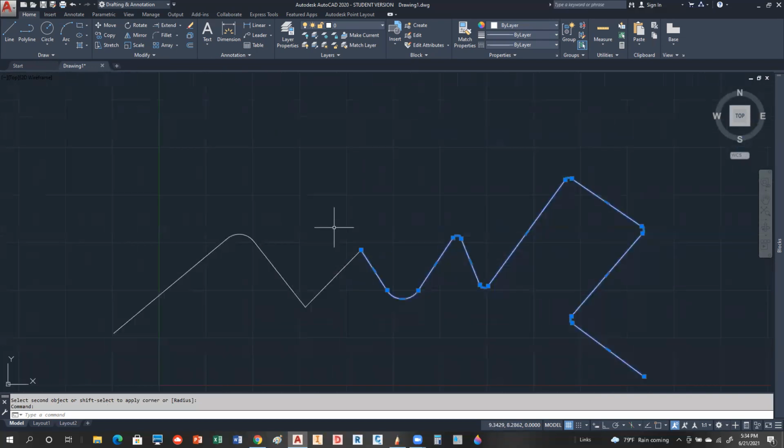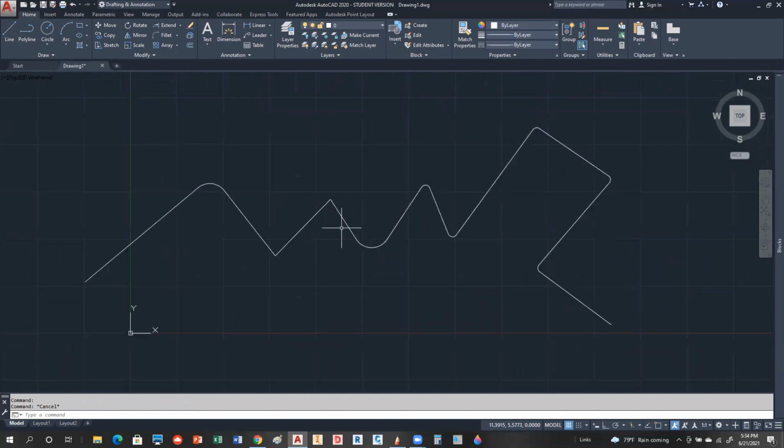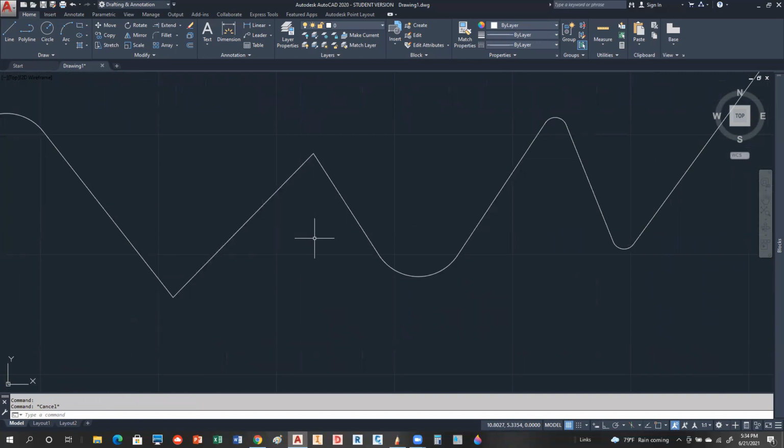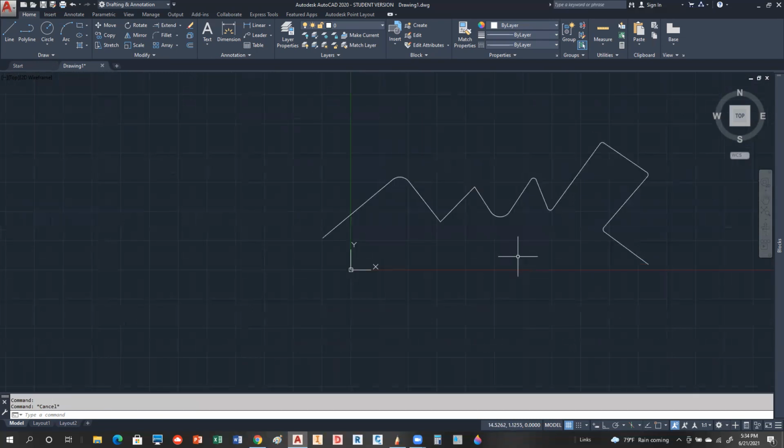So polylines are kind of unique. They used to be tricky, in fact, they didn't like to fillet, but now they fillet pretty nicely the way they work. So you can have all of the vertexes have the same radius, or you can have them all have separate ones. It just depends on how you use it. Okay. Any questions anybody has on this? This is pretty good stuff.